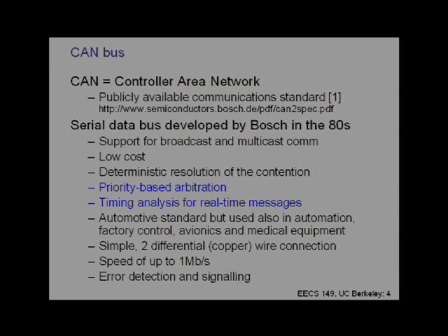And the latency of that should be bounded, obviously, because if the driver depresses the brakes, then you want that to happen in a certain amount of time. So the overall timing includes the timing of the software, which we talked about earlier last week, right? Plus the timing it takes for messages to get through from one node to another.